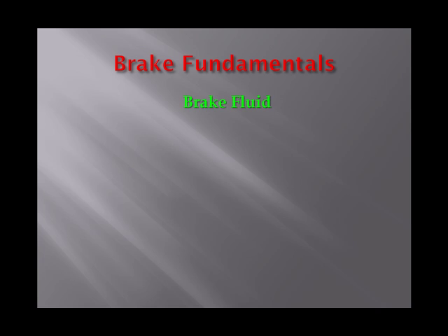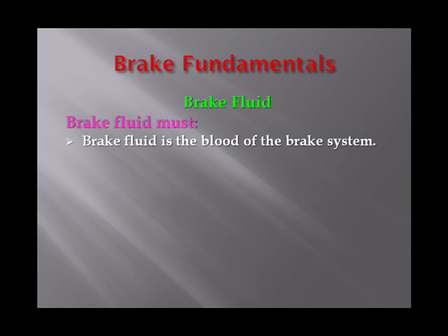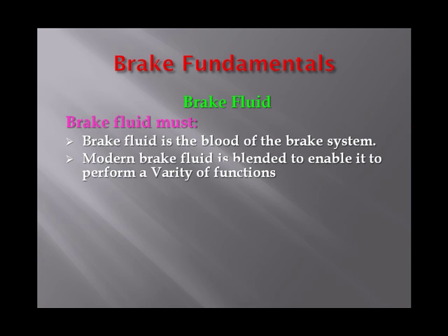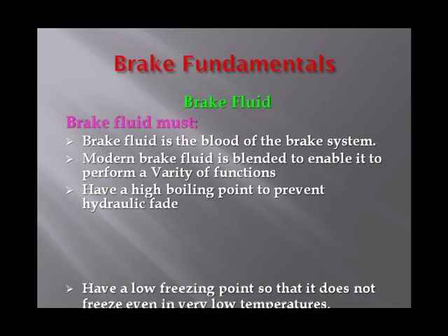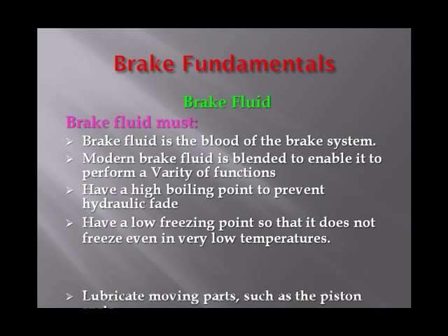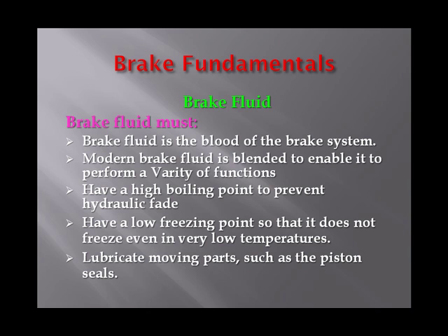Brake fluid. Brake fluid is the blood of the brake system. It is what makes the system operate properly. Modern brake fluid is blended to enable it to perform a variety of functions. It must have a high boiling point to prevent hydraulic fade. It must have a low freezing point so it does not freeze even in low temperatures. And it must lubricate moving parts such as pistons and seals.